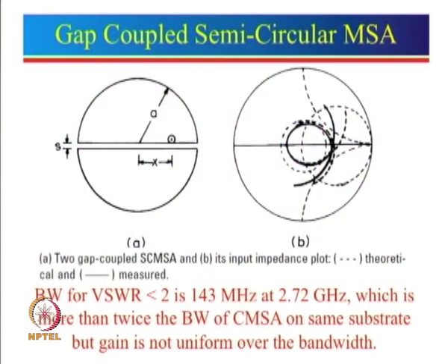Okay. Then we actually came out with another idea when we discussed a circular microstrip antenna as well as a semicircular microstrip antenna. So, what we had seen is that the resonance frequency of a circular microstrip antenna is the same as the resonance frequency of a semicircular microstrip antenna. Okay. So, here this is of the same radius as this here. So, now you might wonder if this radius is same as this, then their resonance frequency will be same. Actually not really, this patch is being fed. So, it is fed with the coaxial probe, and a coaxial probe will have some inductance.